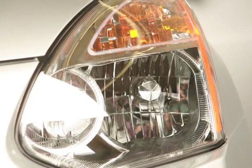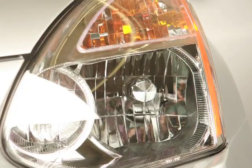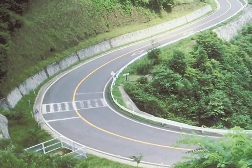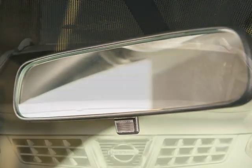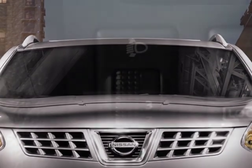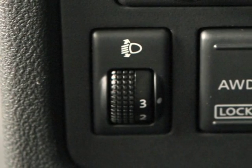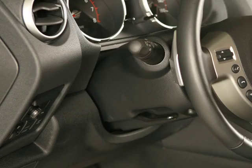Headlight aiming control, if so equipped. This feature allows you to adjust the level of the headlight axis. You may need to do this if driving on hilly roads, if your headlights are directly hitting the rearview mirror of the car in front of you, or the windshield of an oncoming vehicle, creating a glare. The headlight aiming control switch is located on the left of the dashboard behind the steering wheel.